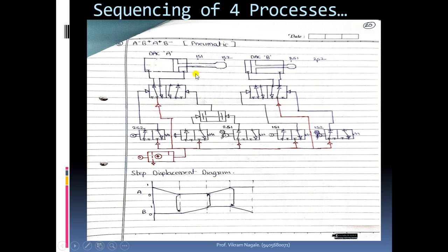Now this is initially extended. Initially extended means what do we have to do? We will have to connect a block whose purpose is to achieve this position. We will have to find a block that gives us extension, because this is the initial condition. The flow should be like this. That means there should be active pressure from the left side of the piston, then only the rod end will remain in this position.